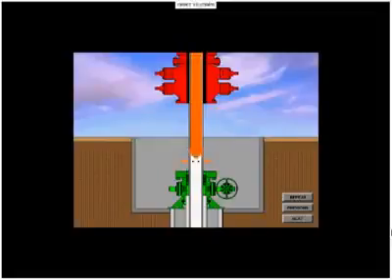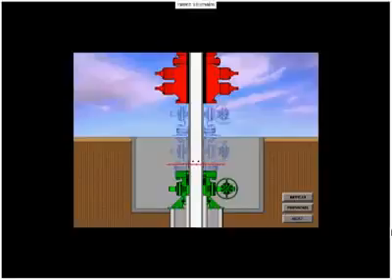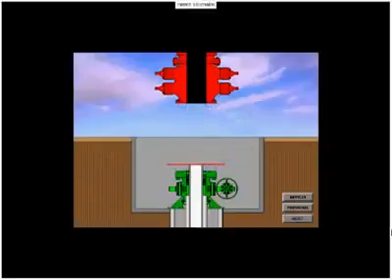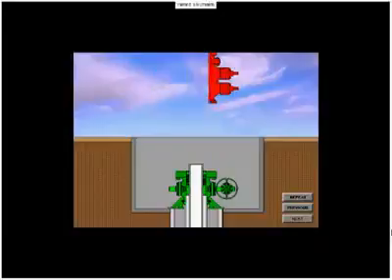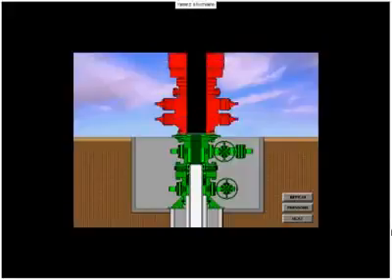Holes are cut in the casing to allow the drilling fluids to drain out of the casing riser. When the casing is drained, a rough cut is made, and the casing spool with a crossover seal is installed. The BOP system is nippled up, and preparation is made to drill out for the production casing string.